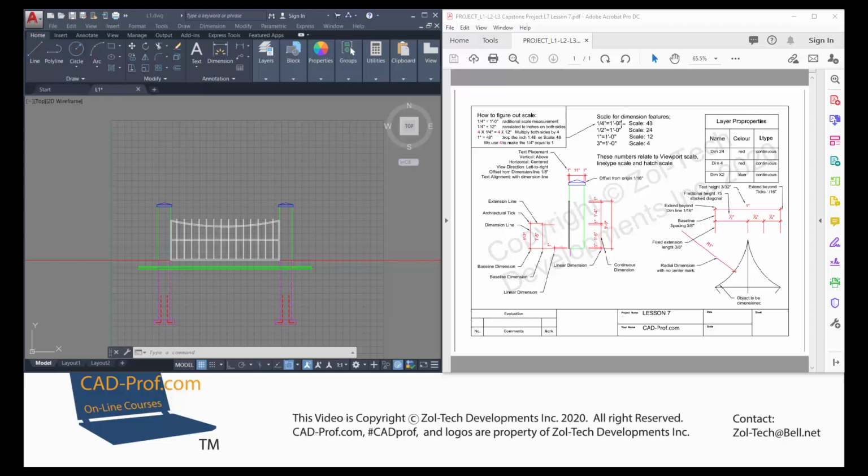So anytime you have a particular scale, you can add this formula to it to actually determine the drawing scale that CAD understands and will be used to represent the images that we'll be zooming in on. This also affects the line type scale and the hatch scale, so it's something that we fundamentally need to know.